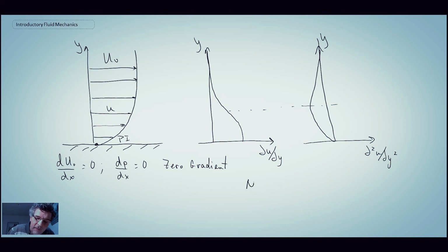There is no separation, so the boundary layer remains attached. And the point of inflection is at the wall. And we can see that here by looking at the second derivative term. We have a second derivative value of 0. And consequently, that's an indication that we have an inflection point. But in this case, the inflection point is right at the wall. So we've looked at the case of a favorable, a zero